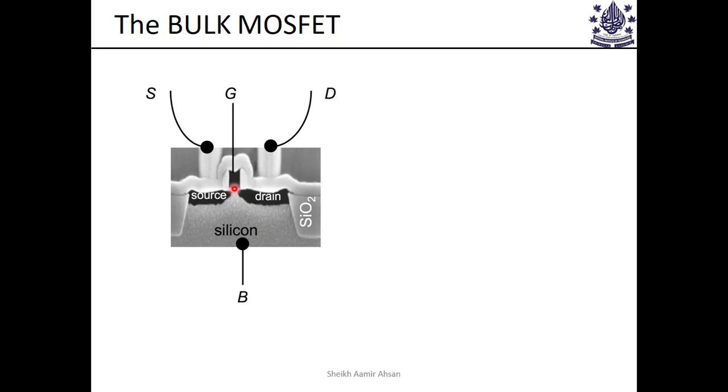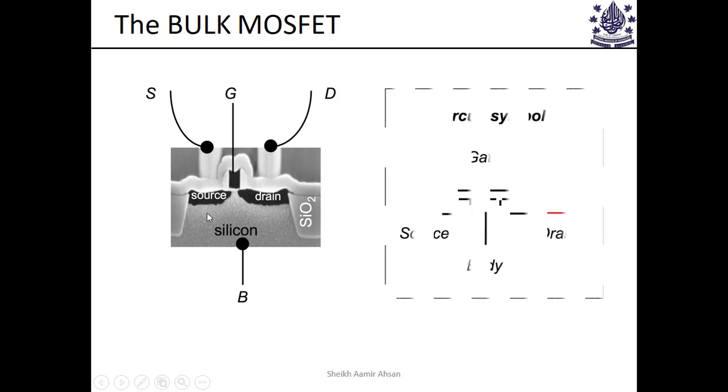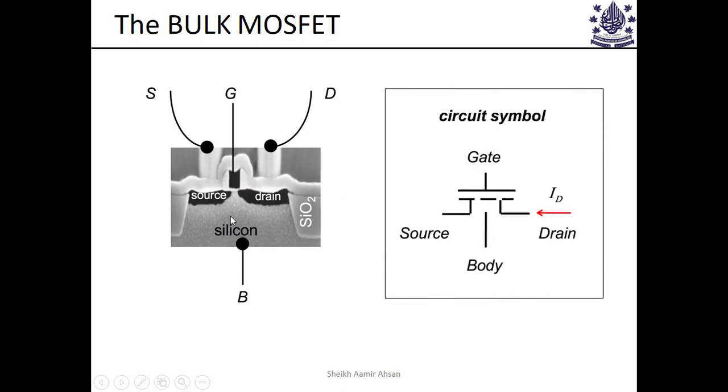This small thing that you see over here is your oxide. It's very thin, underneath the gate, and just this much is the channel. And then you have the usual semiconductor or silicon bulk, and everything else other than this is the oxide. These are different types of field insulating oxides, because you don't want the transistors to interact or get connected with neighboring devices. This is used for insulation or isolation.